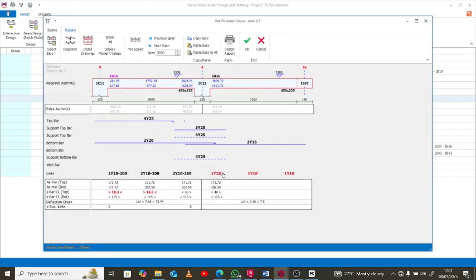So this is complaining about shear here, and I believe it is for the cantilever reasons. Okay, and that's why it is complaining. So we may need to redesign this section to be able to accommodate what is happening there.